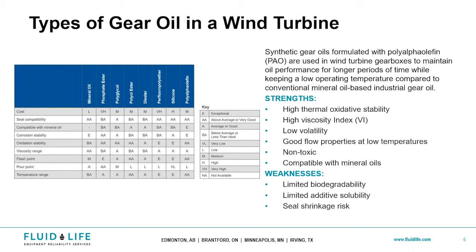So some things you want to check for with a gearbox is micro pitting, white etching cracks that appear on the bearings surrounding the gearboxes, and that could amplify and lead to tooth breakage and other catastrophic failures over time. If you guys aren't aware, gearboxes are pretty expensive. They can range around like $250,000, and then you have to talk about mobilizing a crane. Most sites don't have that stuff ready to go, and they also usually don't have a bunch of gearboxes lying around in the shop floor.